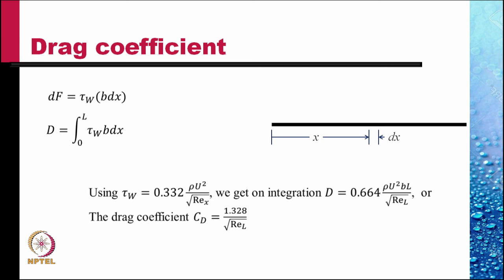We will show later that it is because of the dynamics of this thin boundary layer due to Prandtl. And the dynamics leads to separation from the surface, where the boundary layer does not remain thin and the viscous effects penetrate in the main flow.